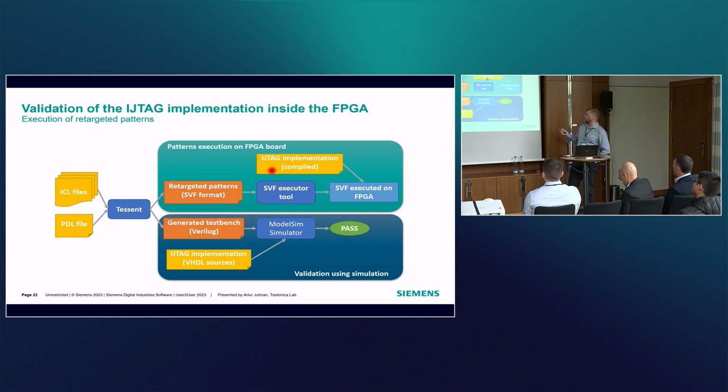The IJTAG implementation would be placed on FPGA for the execution. On the simulation side, Tessent again will generate a test bench, and the same IJTAG implementation would be used as an input to the ModelSim simulator, and we also expect a pass result.